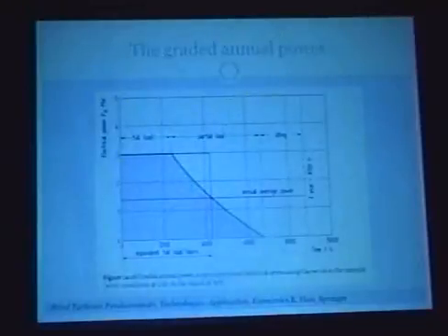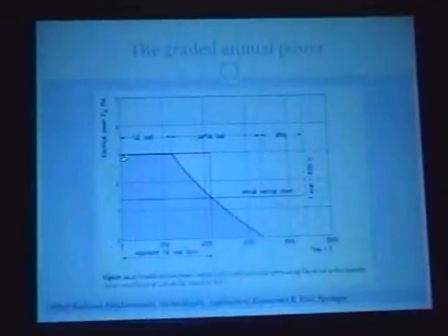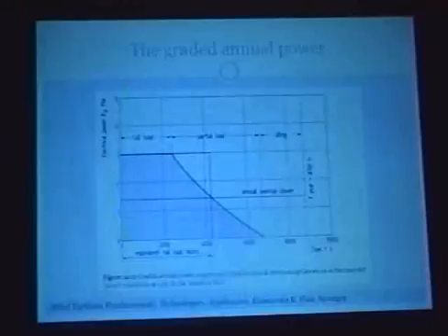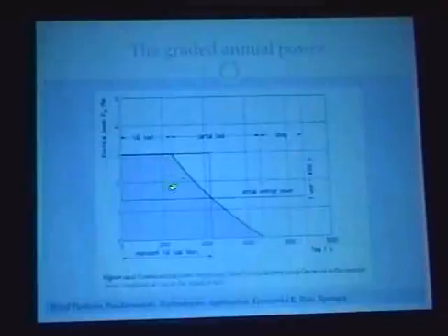So what this is, is the time, and you'll see that this is 1 year. So these are all the hours in a year, and the year is about 8,800 hours. And this is the power that you produce for a given amount of time. So for, say, 2,300 hours, the turbine produces its rated load of 3 megawatts. Whereas for a couple thousand hours during the year, it produces some partial load power that's less than 3 megawatts.